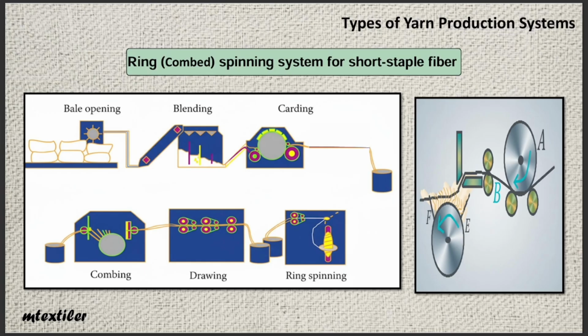In this slide, you can see the schematic diagram of the overall production process for this system. After carding, the combed process is used. Before combed, we can have drawing, and also after it as well. During the combing process, fiber slivers are separated, the fiber bundle heads are combed, and short fibers and waste are completely removed from the main fiber bundle, then joined again to the tail end of the bundle. This process continues at high speed every few seconds, constantly, just like the precise, rapid, and amazing pumping action of the heart showing us the fascinating world of yarn production.